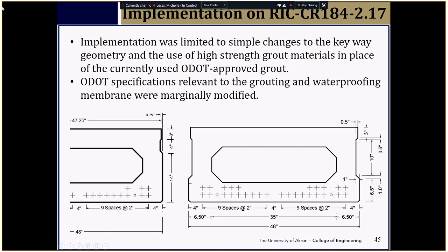On the other hand, if you have a deeper keyway, if the bond between the concrete surface and the grout is reasonably good, if it is still intact, that rotation is prevented. That's number one. Number two, the finite element analysis has shown clearly that the stress intensity for deeper joints is significantly smaller than for shallow joints.